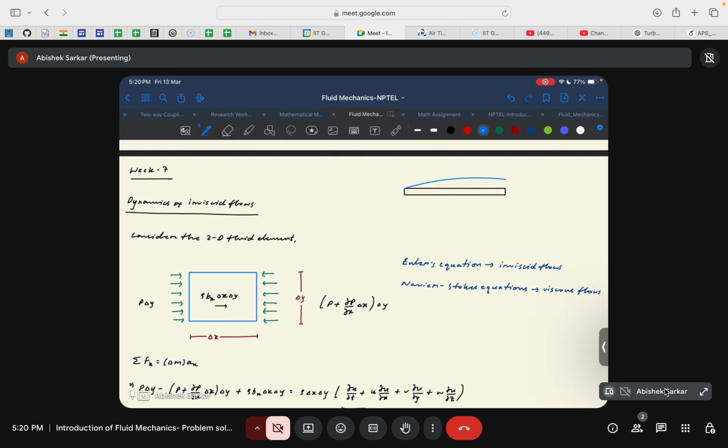What a boundary layer basically is, is more or less a demarcation between the regions of viscosity and regions which can be modeled as inviscid in nature. Let me tell you the difference now. In this boundary layer, all the strong viscous effects that are felt because of the presence of the plate are confined within a very thin region.